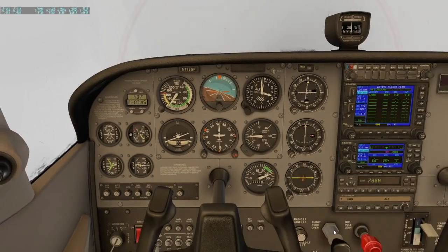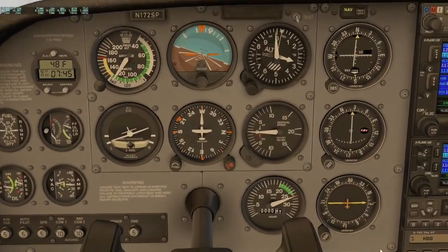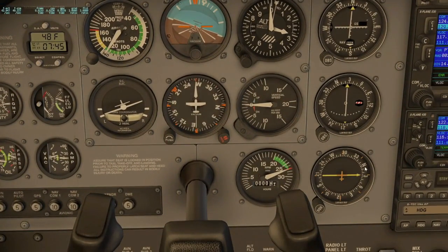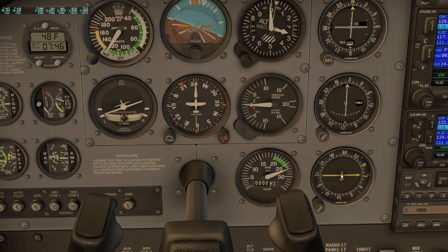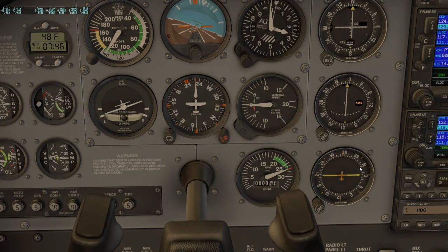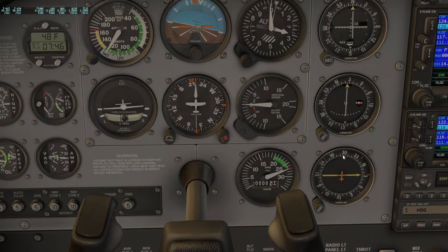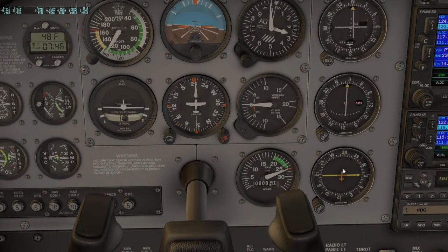Back again. Why am I turning to 210? We're following the steps. 30 degrees, 60 degrees. I'm higher than 60 degrees. I have to go opposite of the inbound radial. Here's the inbound radial in the direction towards the VOR. I'm going to go opposite of it to 300. I'm going to turn left 90 degrees until I hit the difference of 30 degrees here to the 330 radial. Then I'm going to intercept at 45 degrees. Good, so now I've turned.